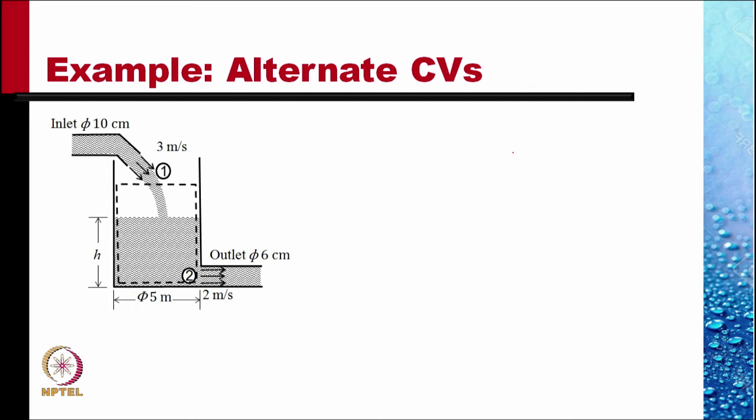The area would now increase to the area of the pipe divided by cosine 45 degrees. But when we find the flow, the vertical component of velocity would contribute to flow across that area, and the vertical component of velocity would be v times cosine 45 degrees. So the product of the velocity and area would still be the same, VA. So we should get the same result.